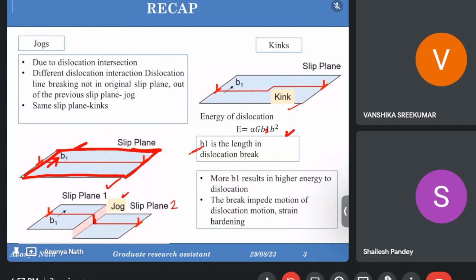They will always try to have a low energy configuration among themselves so that they don't need to move. Because if there is a lot of dislocation density, we have done a lot of cold working, and the dislocations have not arranged themselves, they are at a high energy configuration. The energy associated with each dislocation is very high. Then the result will be a lot of residual stress inside the material.